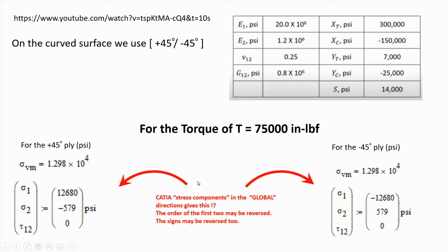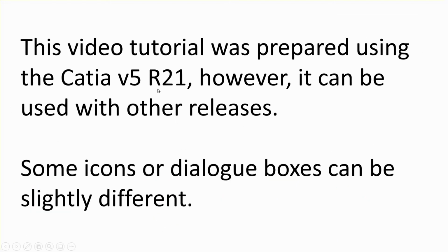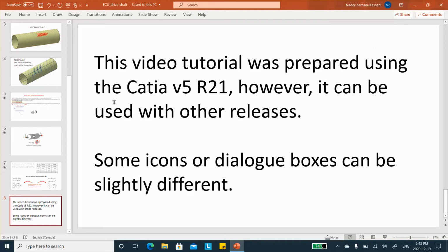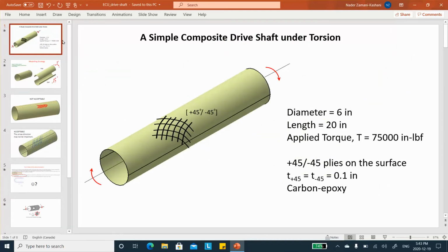Now, the mesostress matches, there is no problem. But this issue of components of stress in CATIA's FEA is not very well documented, and one has to be a bit careful. Finally, I said that this is done on R21, and therefore you've got to be careful. I'll keep this handy because I go back and forth between them.